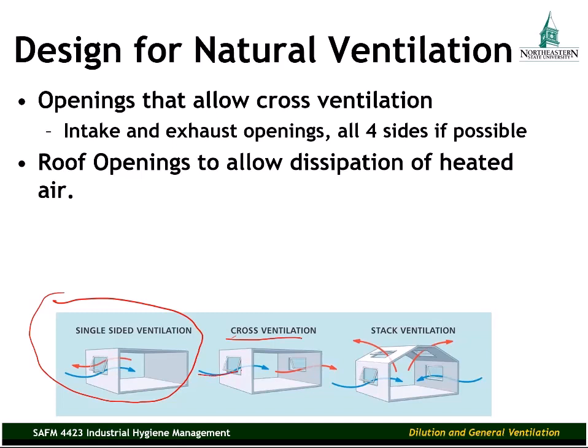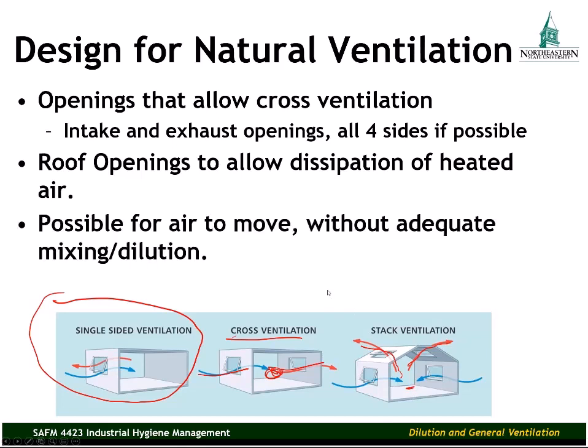We have air blowing in one window and out the other. And ideally, your workspace is going to be in that airflow, in that airstream. Over here, furthest to the right, we have makeup air or supply air coming in through windows and being exhausted naturally through roof windows or skylights that open. That's a good design as well. But if you can, all four sides, openings on the roof to dissipate heat.